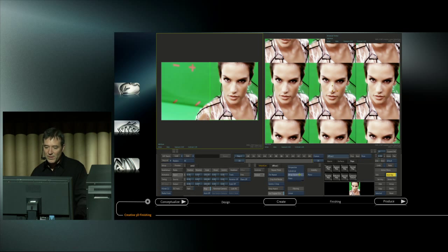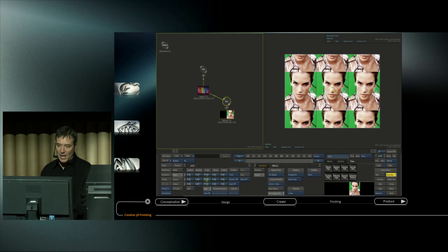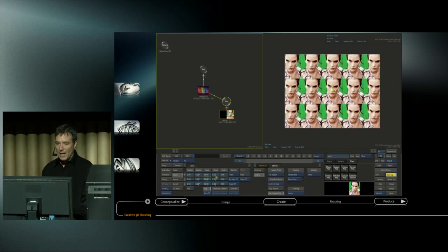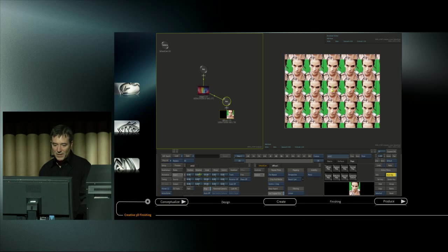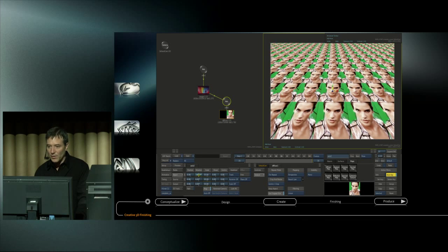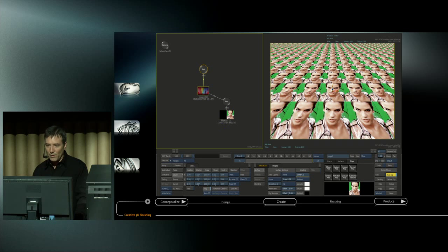Under the mapping choices, we also have something called perspective mapping. So this is another really nice feature. It allows us to take our scene. Let's scale this down quite a bit. You can also scale that down, something like that. And then we'll just rotate that back in perspective. So you can see with a very simple construction here in the schematic view, we're able to create a much more interesting angle with our perspective mapping. So again, it's a pretty nice little trick to do things like that using a different resolution texture, diffuse map attached to our initial film image.